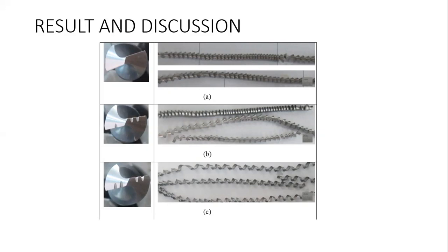thus causing damage to the cutting edge and cutting edge holder. Picture B shows the chip shape from the second drill bit, with two splitting nicks on one side of the cutting lips of the twist drill and one splitting nick on the other. The resulting chips are a long angular thick helical chip and a long angular loose helical chip with a smaller width. The shape of this smaller chip allows easier evacuation from drilling holes.